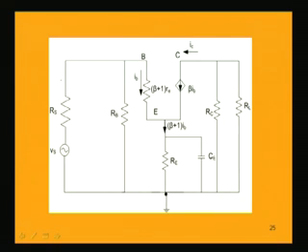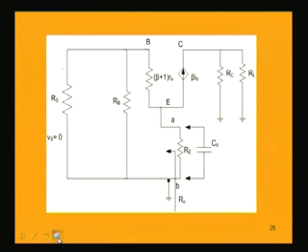The easiest way we will be now adopting is that we will find out what is the effective resistance across this capacitance CE. So, in order to know the effective resistance across this capacitance CE, we just remove this capacitance, open circuit it. I mean at this point we are just disconnecting this CE and looking into the circuit to find out the effective resistance. So, that is what we are doing here.